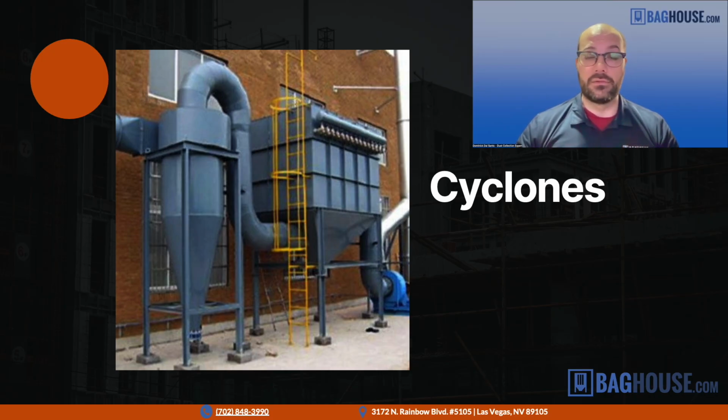So again, cyclones are good for pre-filters, removing most of the dust, and oftentimes they're paired for some process reason, but often they are just used to lighten the load of dust going to the baghouse.